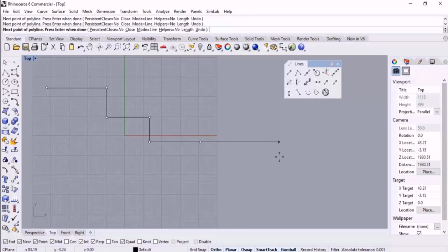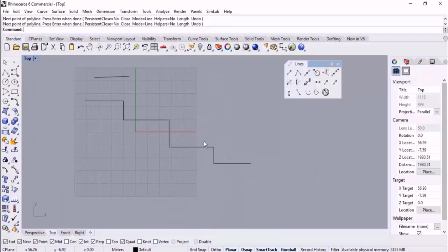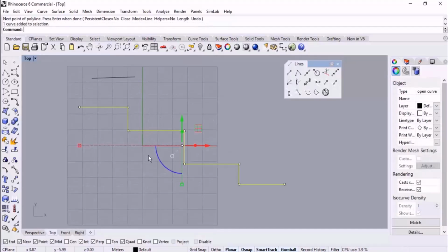Suppose that I'm sketching these curves, I hold down the shift button, and then by accident I release the shift button, and then I need to edit one of the lines. How can I edit this sketch? What do you think? Exactly, we use U. If I type U in the command line, as you can see, undo, then you can just type U in the command line and then press enter in order to undo the commands or the sketched lines, and then start sketching to correct the curve. I press enter, well done. And as I told you before, it is similar to AutoCAD.